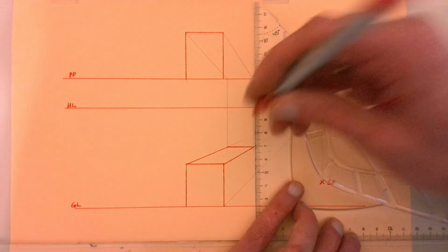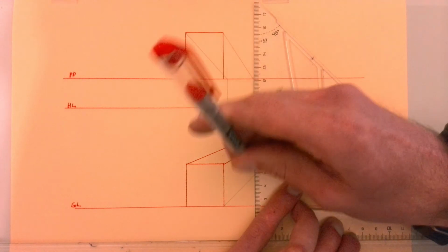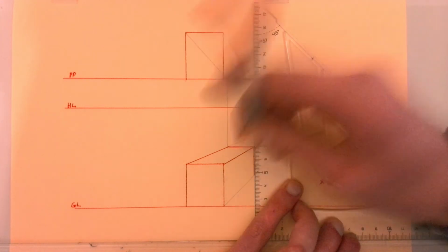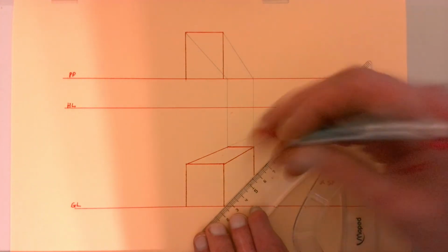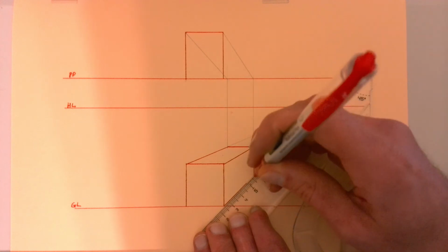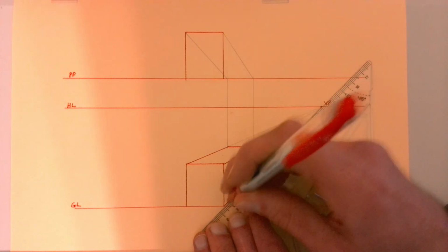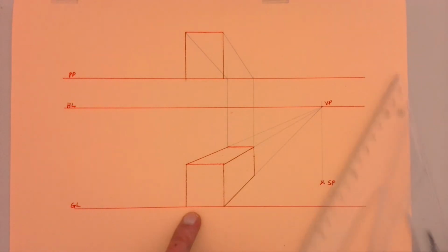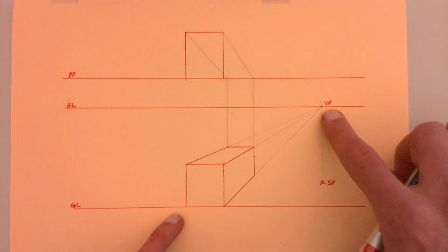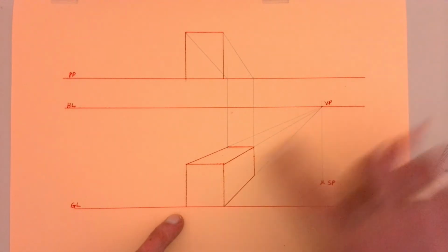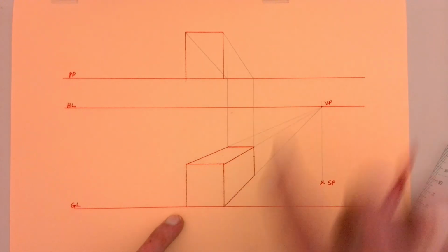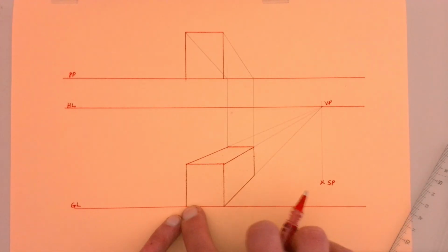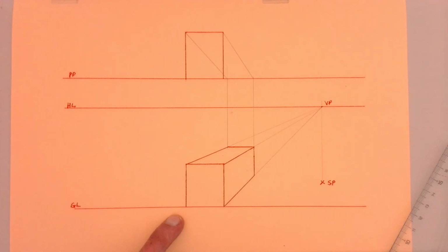So we know that this line over here is going to end in line with this corner, so we can simply draw this line straight down, and then draw this line across to meet up with that point to end it there. And then this corner over here, we're not even going to bother projecting to our vanishing point, because that line over there would fall behind the shape. And in our 1 point perspective, we don't draw in hidden details, so it's not necessary to take that line across. And there we have our 1 point perspective done.